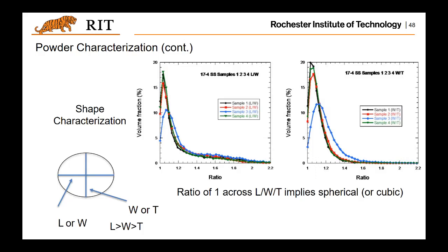So another consideration is the ratio of the width and the height of the powder. If we consider the powder to be an ellipsoid, there will be a ratio between the longer axis and the shorter axis, and that ratio will affect the volume fraction.